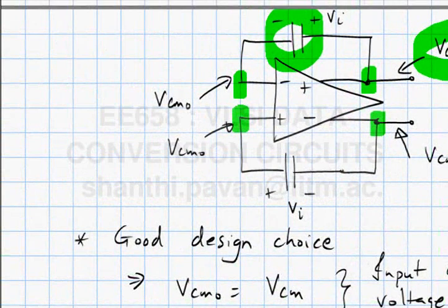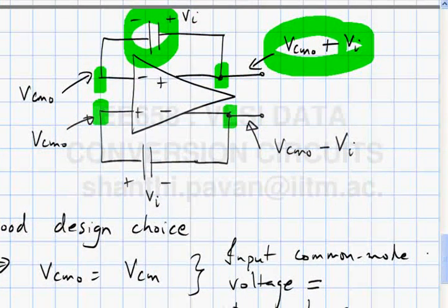One thing here is that there is no gain, right? So whatever input is there, the output is the same as the input, except that the impedance is very low, so that this can now drive other circuits. Can somebody comment on what current is being supplied by the op amp? No current. Why?